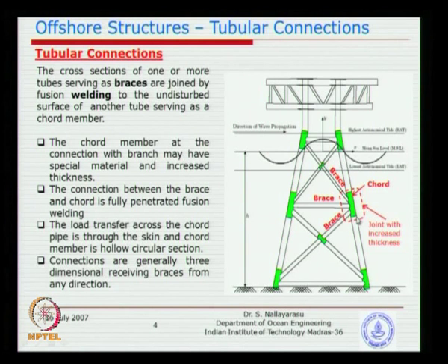And always remember, in offshore construction we do not permit bolted connections. They cannot be sustained because of the nature of the environment we are in. If a bolt fails because of corrosion or movements, the structure will fail. So we always need 100% fusion welding. That means it is not even a fillet weld; you need a penetration weld, which actually makes the welded connection stronger than the parent plates.